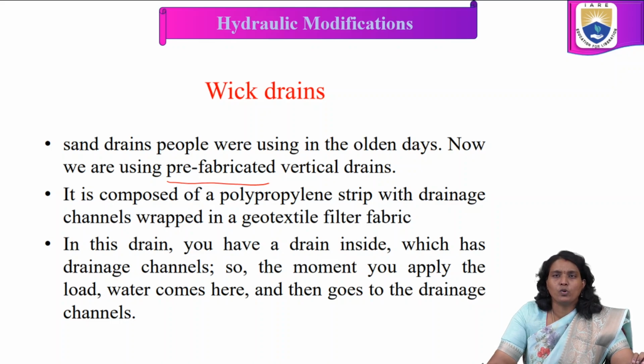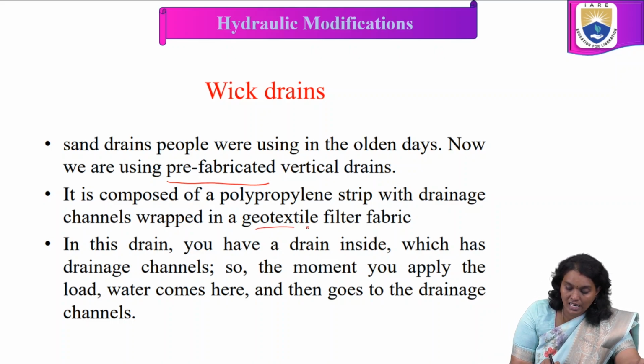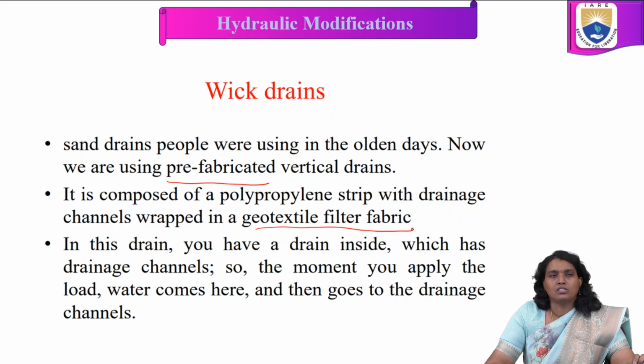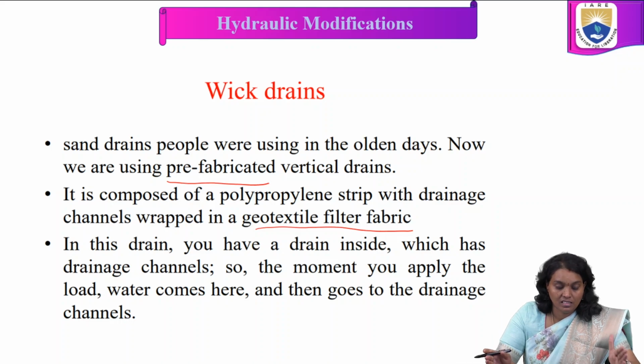These are composed of a polypropylene strip with drainage channels, wrapped in a geotextile filter fabric. The type of geotextile filter fabric used depends on the geo conditions of that particular region.